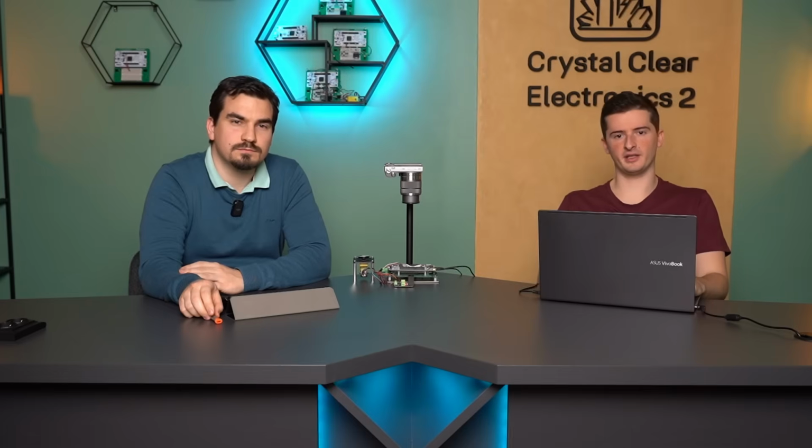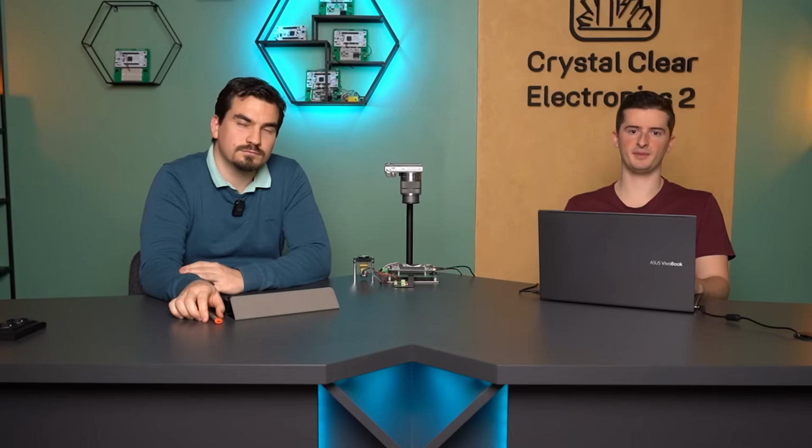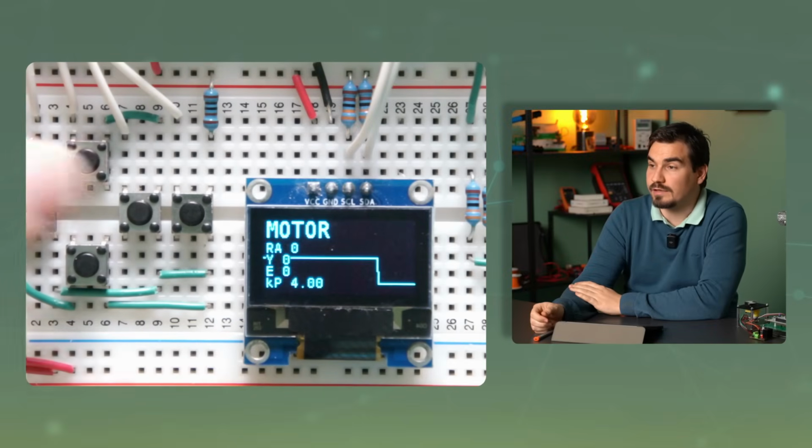Upload the example program Lecture 19 P controller at Ziegler-Nichols to the development board. Here we switch a square wave signal to the motor. For 1 second the set point is 0, then for 3 seconds 50 RPM. We can adjust the Kp value with the up and down buttons. Increase it until we see a continuous oscillation on the display. Bence, please run the code and increase the Kp value.